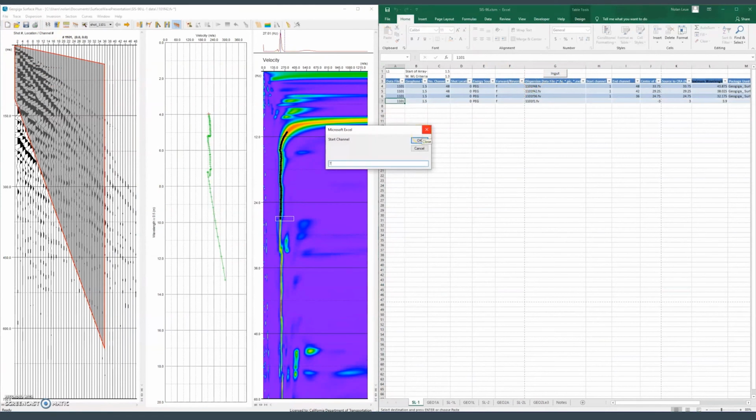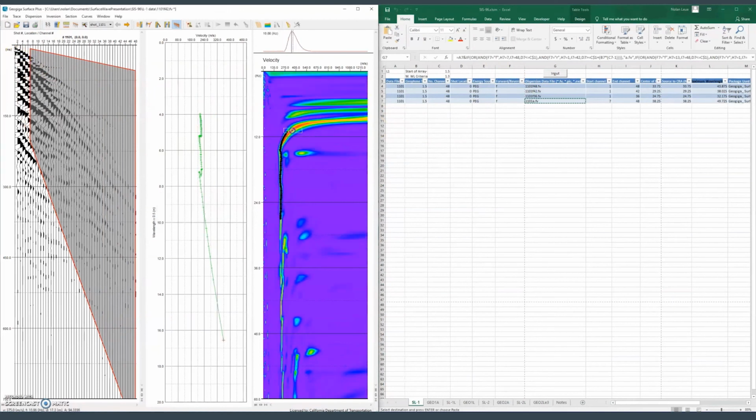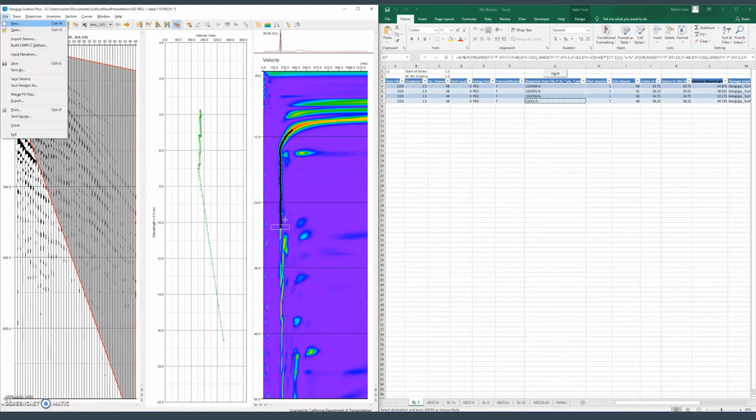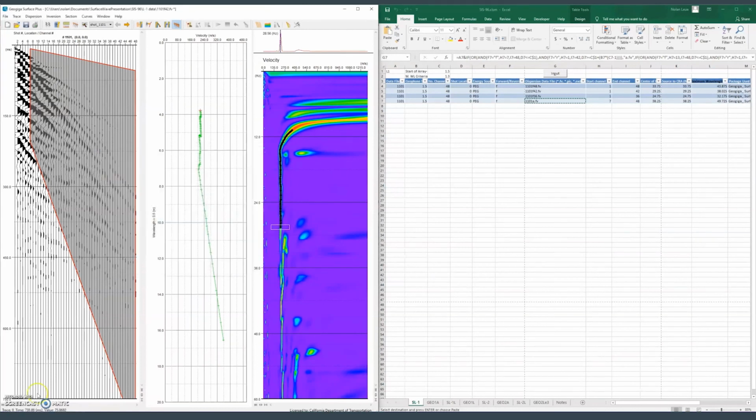Depending on the energy source used for a given shot record, mini dispersion curves are selected and saved. Larger energy sources, such as an accelerated weight drop or 20-pound sledgehammer, will utilize most or all geophone traces to hopefully image lower frequency, greater depth bands of the dispersion curve. Smaller energy sources, such as 3 or 10-pound hammer, use less traces, focusing on high frequency signal near the shot location in order to capture shallow velocities.